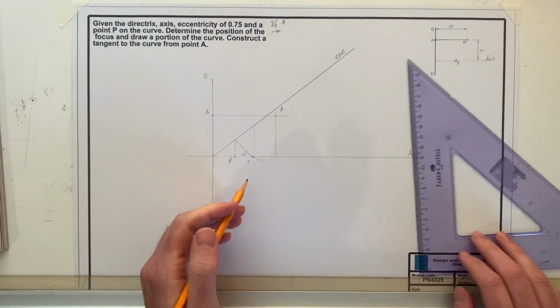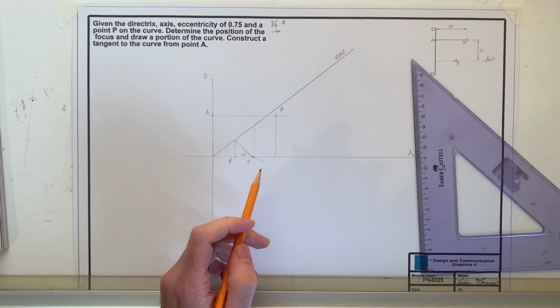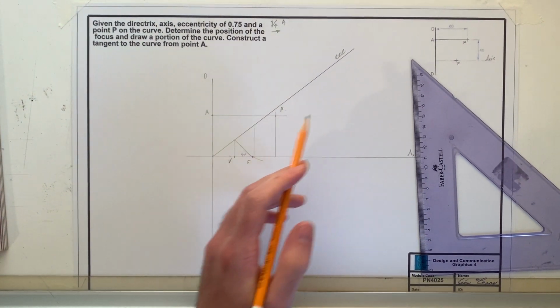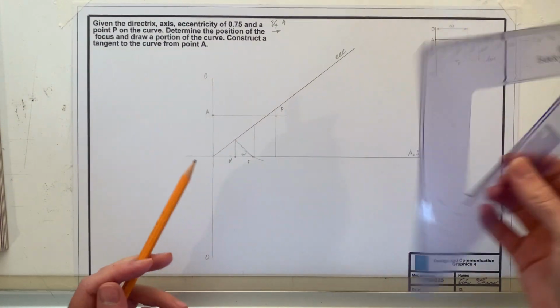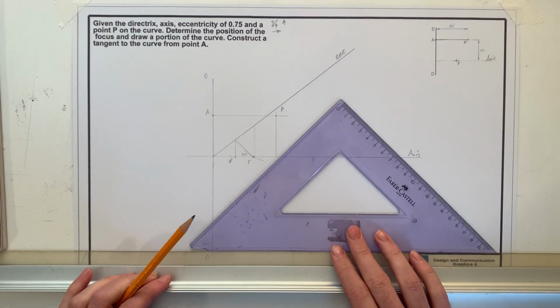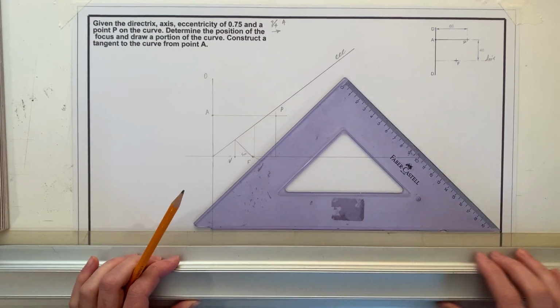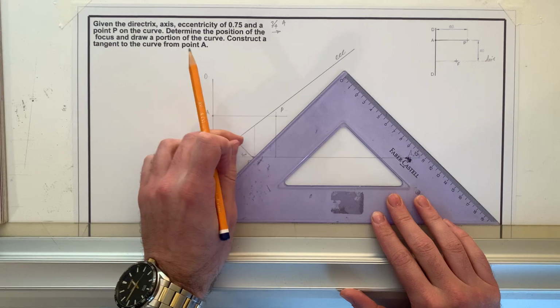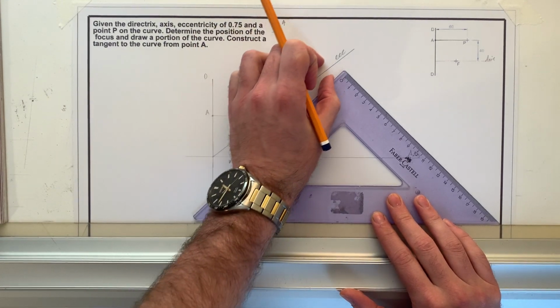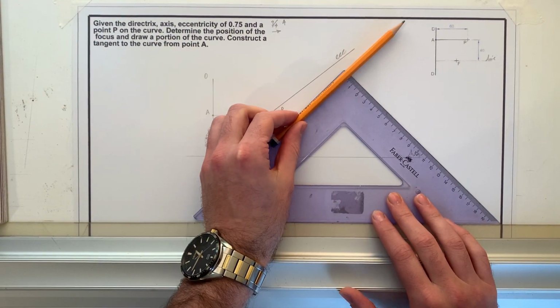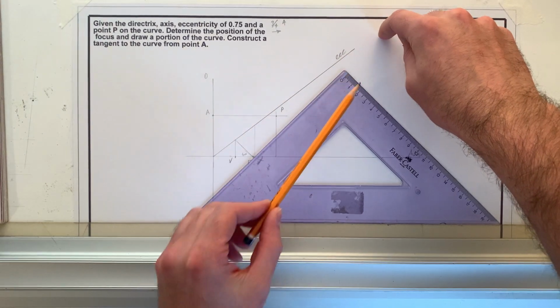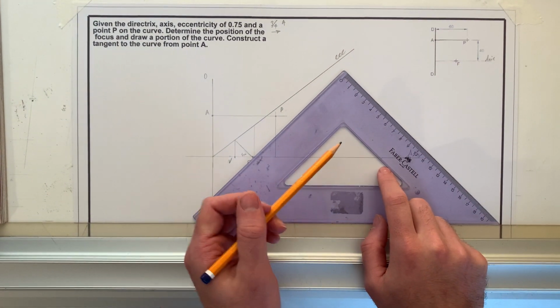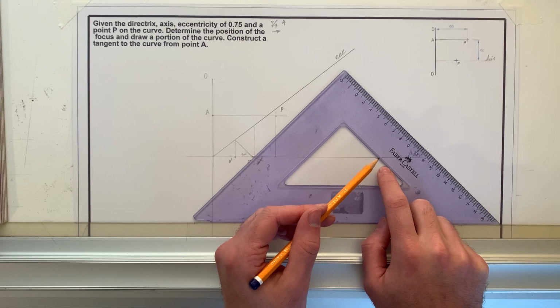The great thing when you're dealing with an ellipse, as long as it's small enough to follow out this construction page, is if I go up at 45 degrees from the focus in the other direction, where that eventually makes contact with the eccentricity line, you see how it's slowly becoming closer. When that finally intersects, so they'll probably meet up here somewhere, and I drop that straight down, then I have my focal point on the opposite side of my ellipse.